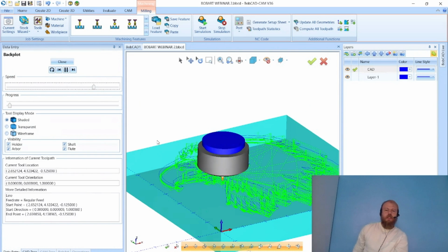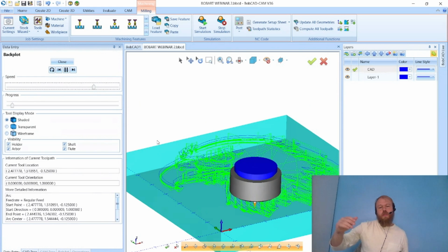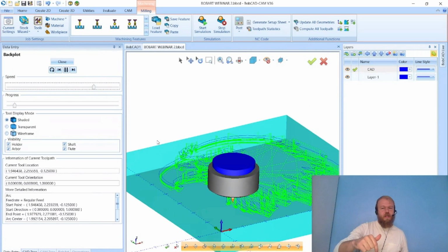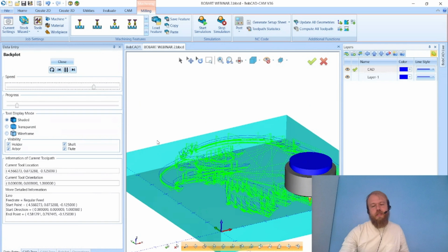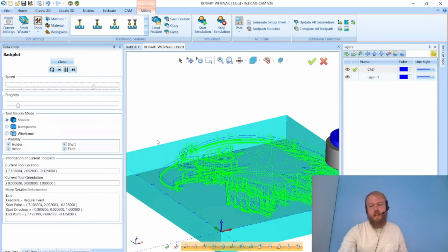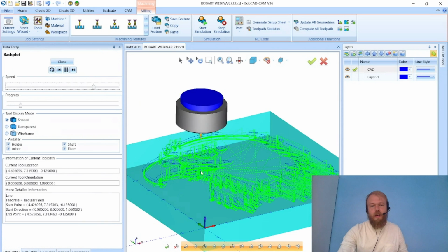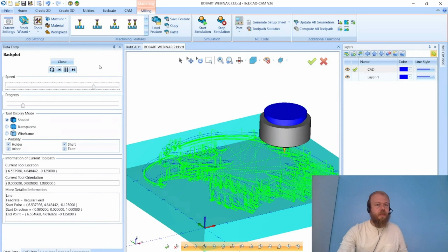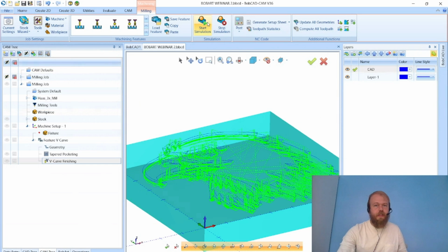So yeah, I'm pretty sure this is going to be 3-axis technically, because when you follow the tapered wall into a corner and it goes down in Z, it can move in X and Y. So technically you'll have a little bit of 3-axis toolpath, 3-axis G-code for your machine here with this V-carve operation. And we'll take a look at it in our simulation here by going to the top, clicking on Start Simulation.